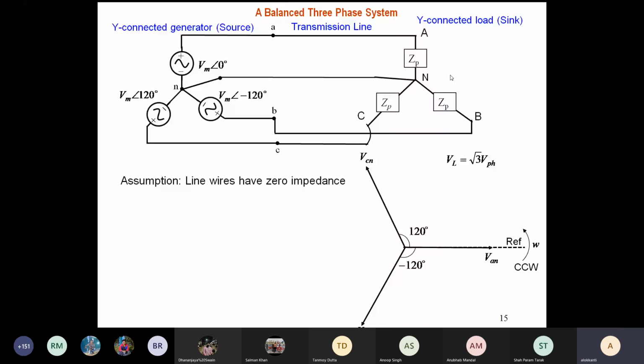Now this power that is transported from the power station to the load, or to the consumer, is through the transmission lines. These overhead lines on the transmission towers, I showed the pictures yesterday. Any line will have its own impedance. It may be 100 kilometers, 200 kilometers. If the power from Jharkhand is transported to Delhi, it may be a transmission line more than 1,000 kilometers long. And you must realize that since it is a piece of wire, it will have its own impedance, which you cannot neglect.